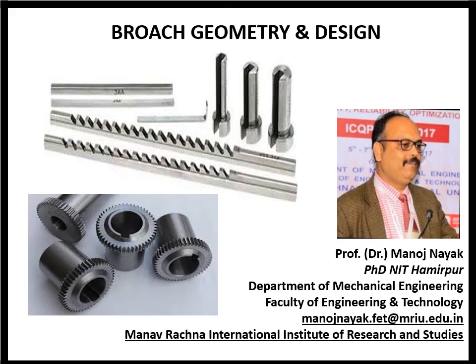Now we are into the next part of this presentation. We will discuss the design aspects that need to be considered for designing a broach: several parameters, cutting parameters, the complete tooth geometry, and finally the length of the broach tool has to be decided, which will take into consideration the load and the cutting forces which are generated due to the broaching operation.